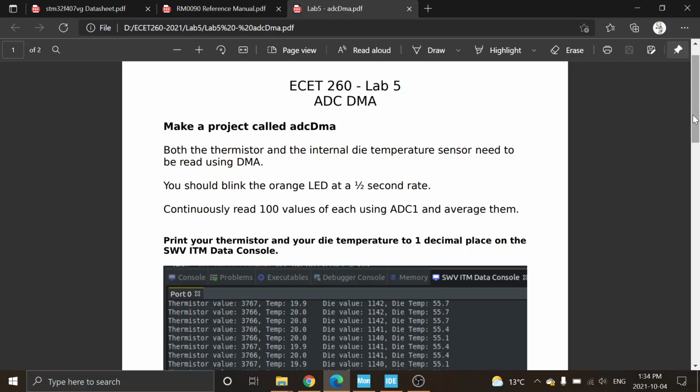Our thermistor is pretty standard on the values. Depending on the board, the one I have here I think reads around 31 degrees. I have one that reads 55, and one that reads about 70. The documentation says plus or minus 40 depending on yours, but it should be pretty consistent after that from whatever your base temperature is.